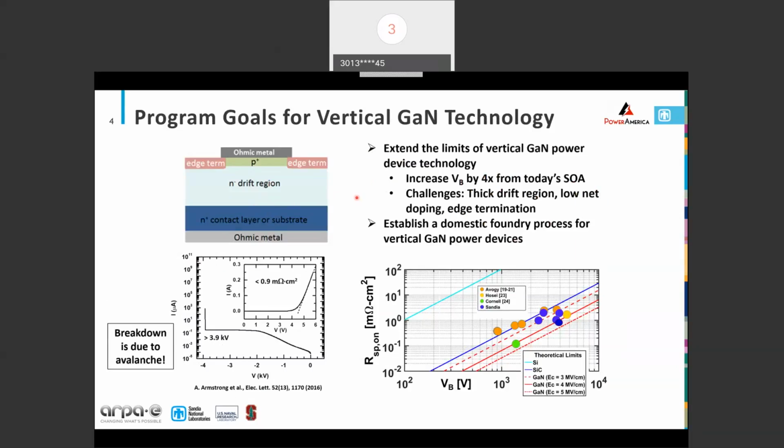The P doping can be a little tough. The magnesium dopant in gallium nitride is a deep dopant, so there can be some challenges with this. We are doing experiments looking at these anode designs and so forth. You don't want to make it too thick, but you want to make sure you have enough holes to inject across the junction. And then the ohmic contact can be a little challenging. I'll mention we do a lot of work on AlGaN also, so that the band gap gets wider, and then the P-type gets even tougher. But I think in GaN it's challenging, but there's a pretty good handle on it, and the devices clearly work.